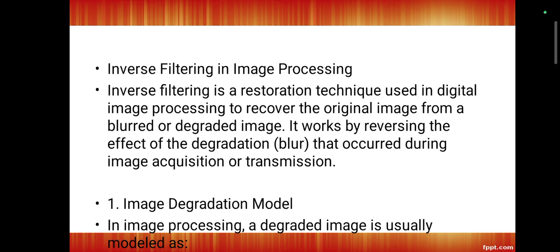And the Wiener filter is not an adaptive filter as it assumes the input to be stationary. This filtering takes a statistical approach to solve its goal. The goal of the filter is to remove the noise from a signal. Before implementation of the filter, it is assumed that the user knows the spectral properties of the original signal and noise.